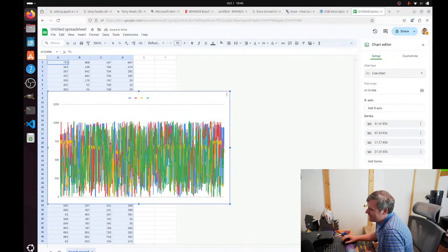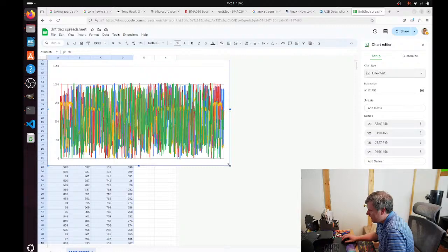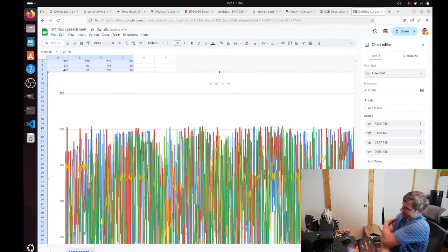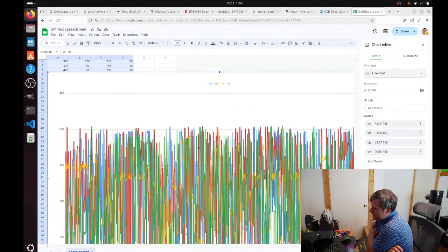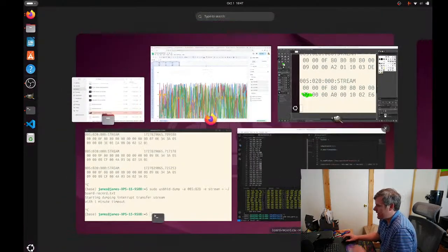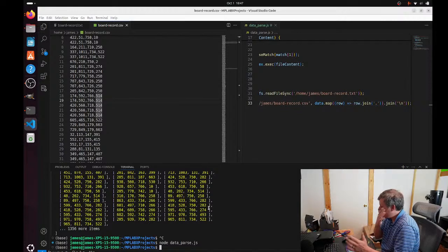Okay, so I think what I'm going to need to do is I want to try to re-encode this actually as binary, like concatenate everything together. I'm hoping what they've done is they've taken the three accelerometer values and packed them together into the 40 bits of data broken across the 16 bit values. And so if I can see where,